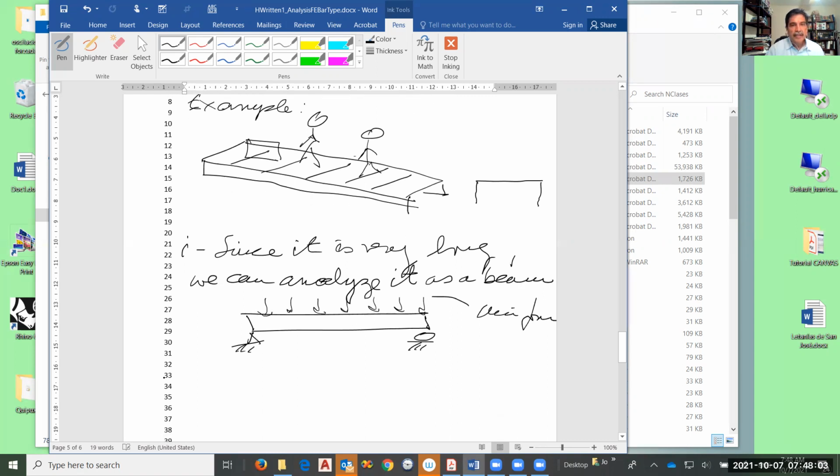What else? Do you think the section along the length of this bridge is uniform? Probably in here, you will increase the material, because here you will have these supports. Here you need to make a hole to include a pin in order to support the bridge, right? So probably you have to increase the thickness of the material in this area.